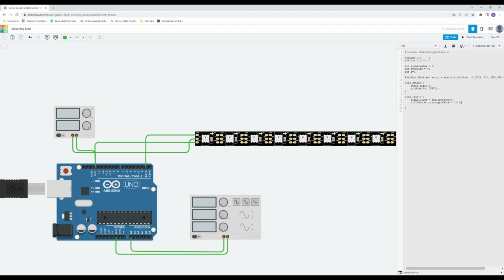And let me explain why this is. So we are going to have 10 LEDs and we are having 51 here. The signal value that we get from the ADC is a value from 0 to 255. And we need to convert this value to represent one of these LEDs. So as the value is higher, we need to turn on more LEDs.